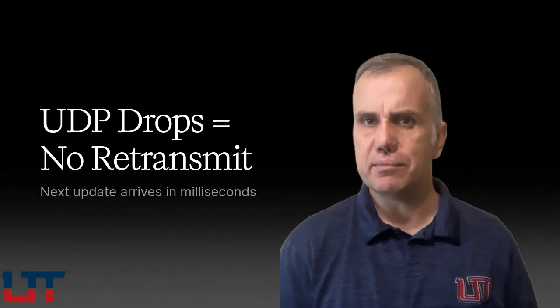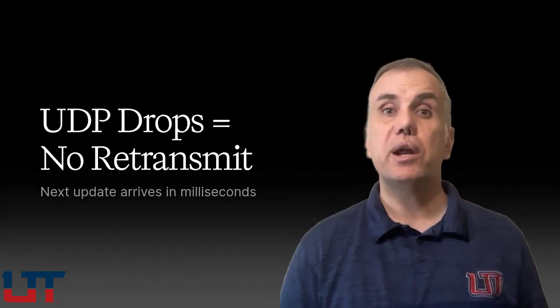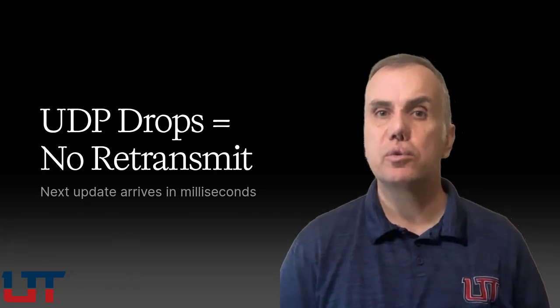In OT, Ethernet IP uses UDP for implicit messaging, the high-speed cyclic communication where a PLC sends a status update to an HMI dozens of times per second. At that rate, losing one packet doesn't matter much. By the time the retransmit would arrive, there's already a newer reading available.